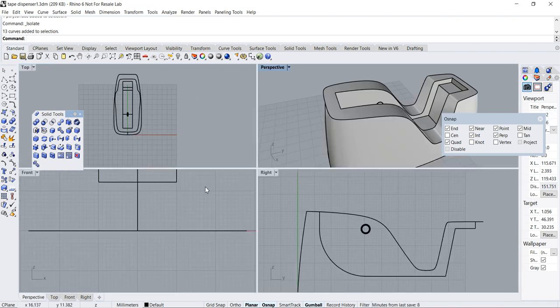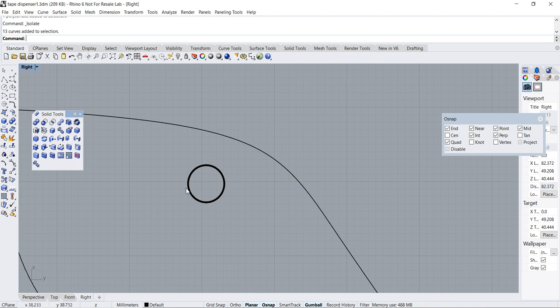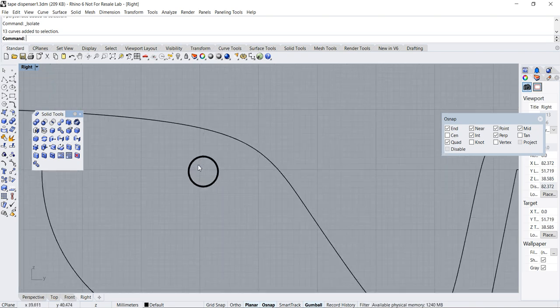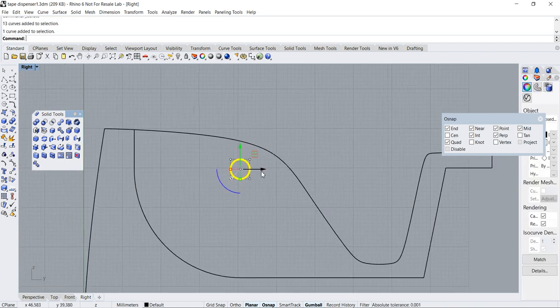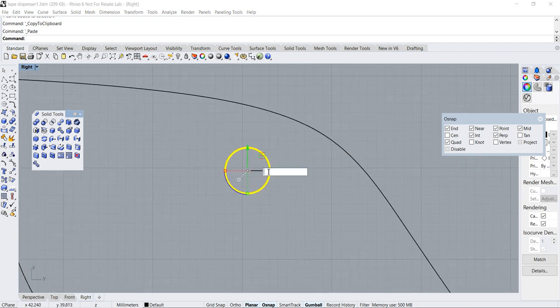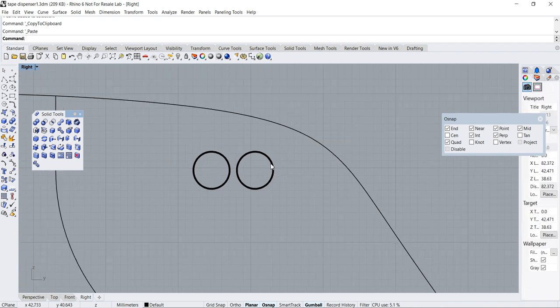So let's start. This is the center portion where the wheel will sit on. This is the width, so I'm going to make a copy of this, paste it, and then move the copy a distance of say 6 mm away. Then I need to create some tangent lines over here, and I can do so by using the line tangent to two curves command.